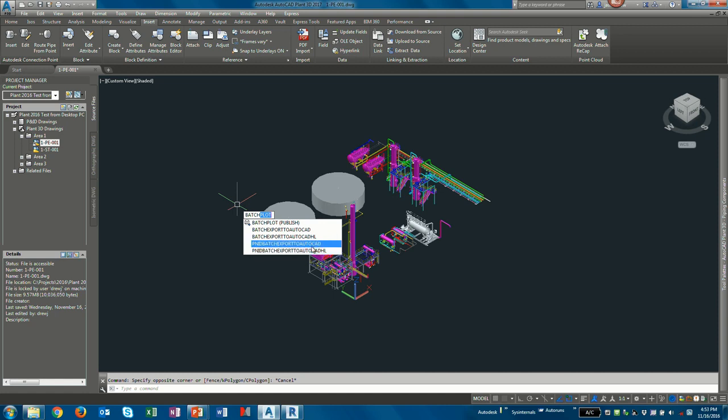The HL is called a headless. What that is basically, if you're going to do this overnight or something where you're going to use Script Pro or something like that to launch Plant 3D, if you run the headless command, it's just going to do it in the background, and you don't have to click anything. So he said that was sort of an automated version if you're going to do it without intervention of anybody. When it runs through that process, you're going to have a destination folder where you can specify where those drawing files are going to be located.